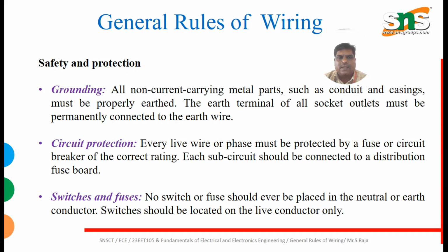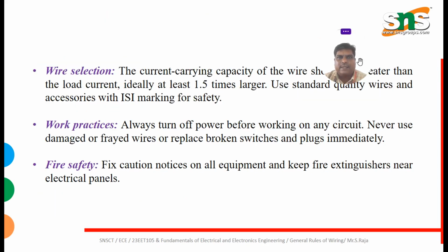Switches and fuses: no switch or fuse should ever be placed in the neutral or earth conductor. Switches should be located on the live conductor only. Wire selection: the current carrying capacity of the wire should be greater than the load current, ideally at least 1.5 times larger. We use standard quality wires and accessories with ISI marking for safety.